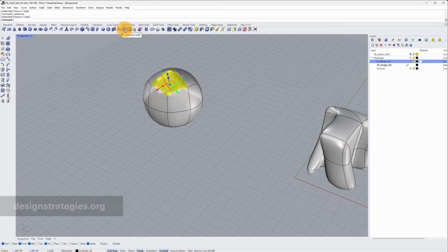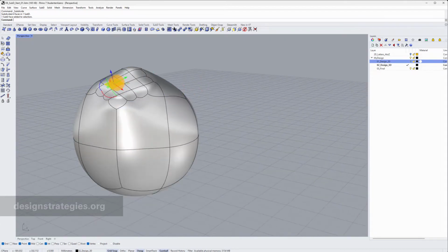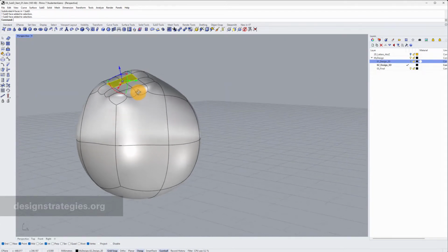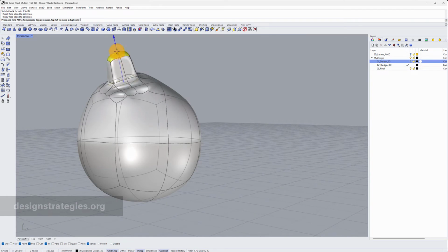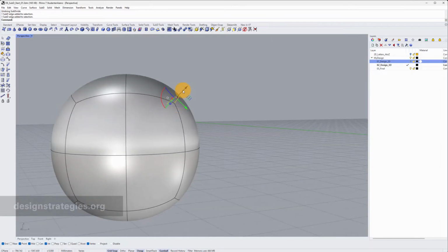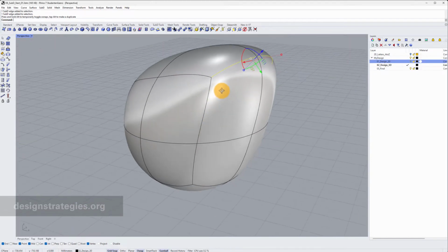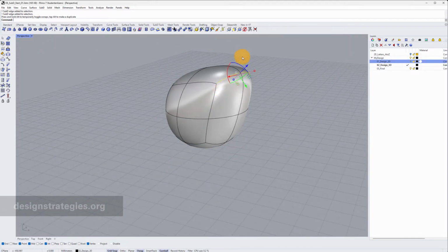you can also select this and subdivide this part. I just do this somewhere like this, and then you can take a smaller part and, for example, extrude only this part, or I go back and select an edge, for example, like this, and then extrude or transform this edge.